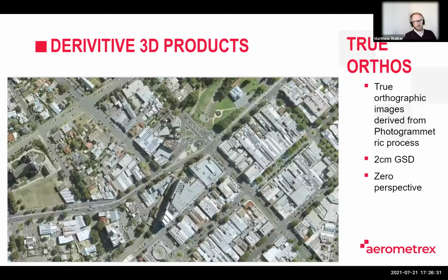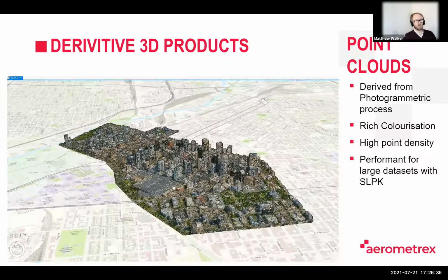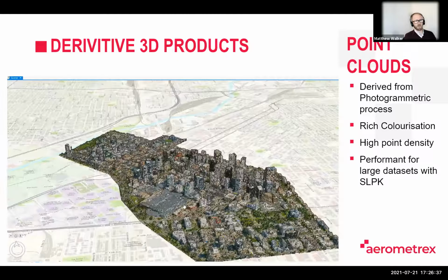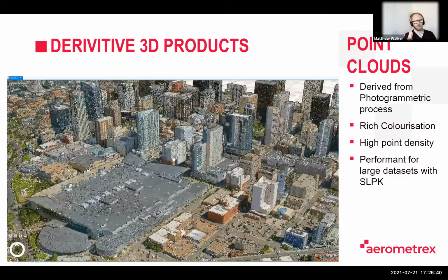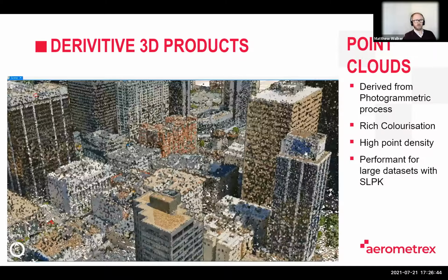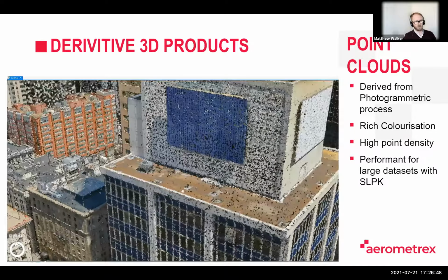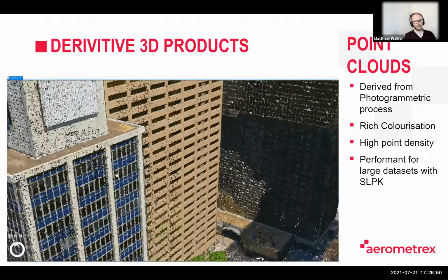Point clouds are also able to be extracted from the photogrammetry mesh. This is just a preference of workflow. Some people like to have point clouds that suit the software pipeline that they have. The same mesh content, which is highly textured, can be converted into a colorized point cloud. And that sometimes works better for different packages and systems.